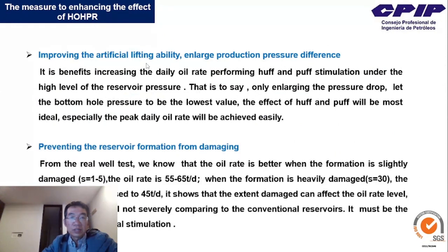Improving the artificial lifting ability in large production pressure difference. It benefits increasing the daily oil rate performing huff and puff stimulation under the high level of the reservoir pressure. That is to say, only enlarge the pressure drop, let the bottom hole pressure be the lowest value. The effect of huff and puff will be most ideal, especially the peak daily oil rate will be achieved easily.